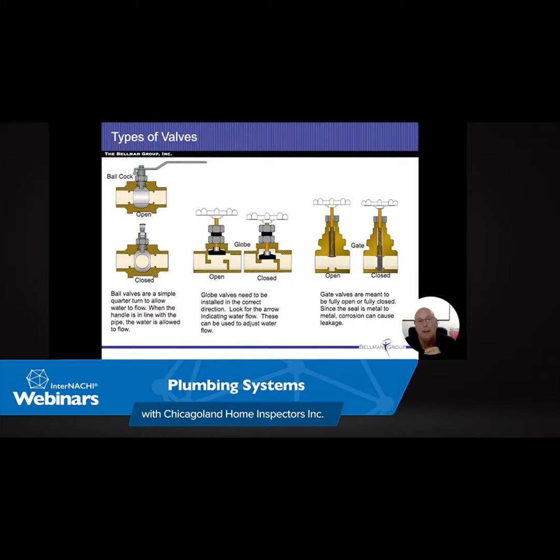This is what an air admittance valve looks like. So whenever there's gas pressure or something coming in there and smells, it's going to force everything shut so that those smells can't escape. But as water is running and it creates a negative pressure inside the pipe, that cap is going to lift up, and then it's going to allow air to enter, so we're going to break up the siphon. And again, it's just pieces of plastic or whatever. Some of them are spring-loaded. They're sliding on top of each other. Moisture's going to be there. Corrosion's going to happen. Eventually, they're going to be stuck in either the open or closed position. There's not a lot of pressure to move these things.